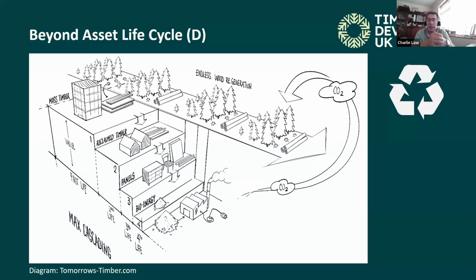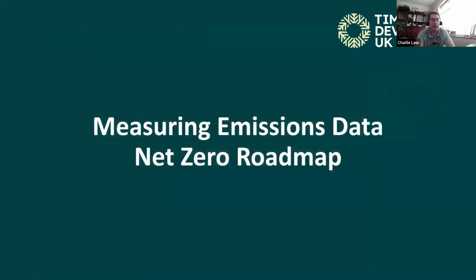For example, reuse of an engineered element, or the use of recycled wood chip for panel board manufacture or animal bedding is sort of offsetting the use of virgin products. So that would be a credit for avoiding virgin wood chip sources, or if we're burning the timber, so it's used as biomass fuel for energy production, that receives a credit for avoiding production of grid electricity and thermal energy from, say, natural gas, or in some cases, other countries, it might even be coal still. So it gives you that impact guidance. It's a little bit woolly because it doesn't actually form part of the calculation. It just gives you some other key benefits.